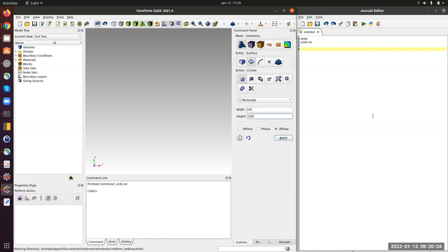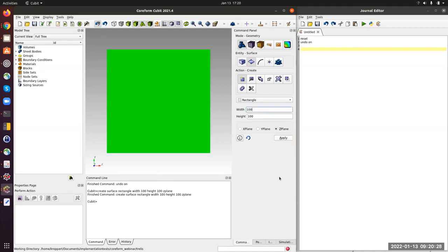So basically here everything is in SI consistent units, so it would be in meters now. However, I scale it down before exporting the mesh. I scale it down by a factor of 1/1000 to have it consistent with our simulation software, to have everything in meters. Okay, let's click apply, and this is our air domain.